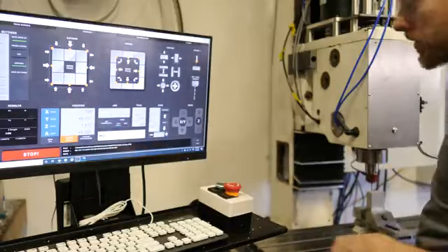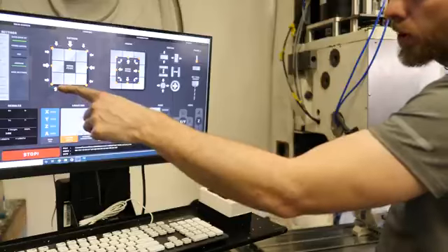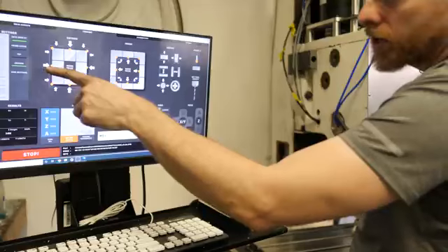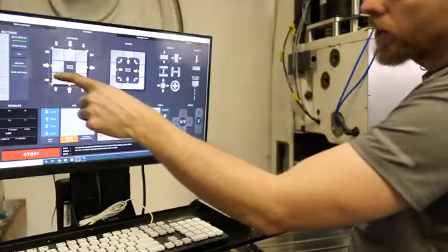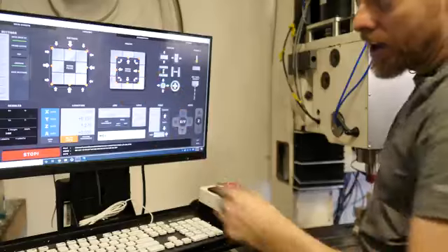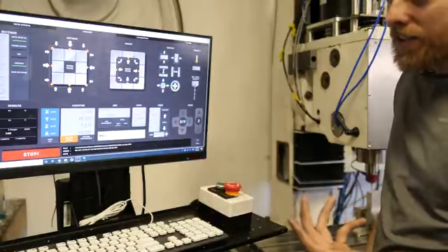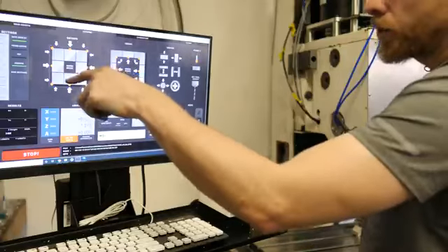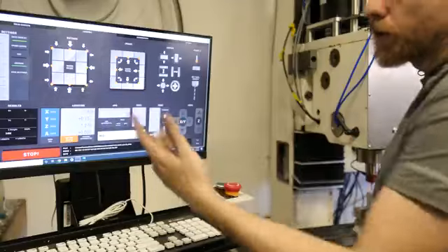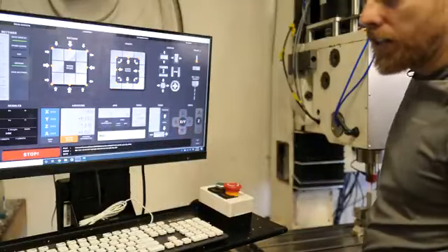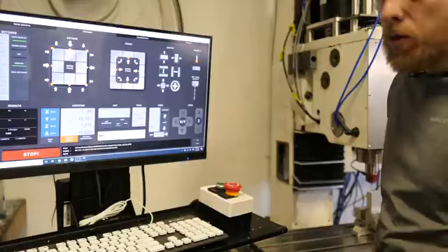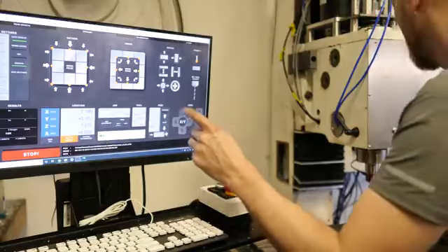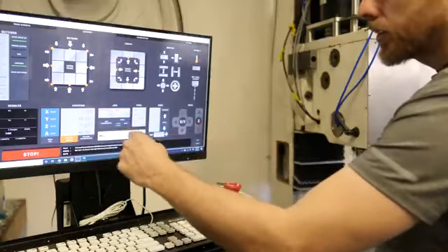Based on these defaults, the probe, if this is the corner of my part, is going to move over this direction and this direction by 1/4 of an inch. It's going to move down 0.4 inches, and it's going to move over at least 1/2 an inch, and if it hasn't found the part by then, it's going to give up. And then it'll come up over the part and do the other side. So this corner probe will do both corners at a time. It'll automatically set those 0 points in your X, Y, and Z coordinate system. And it'll do it based on whatever coordinate system you're in at the time. So let me press the button, make sure everything else is good.